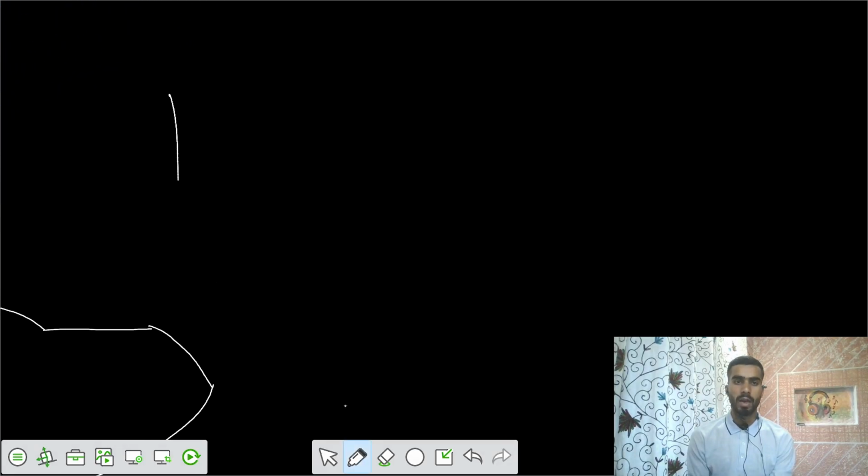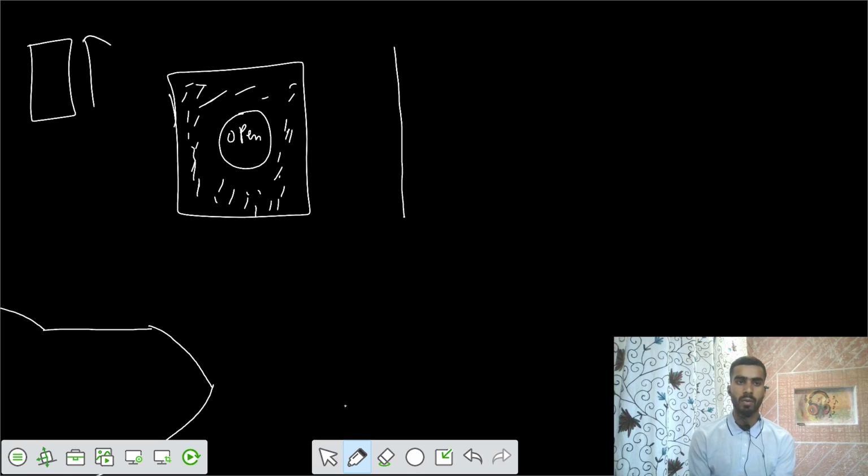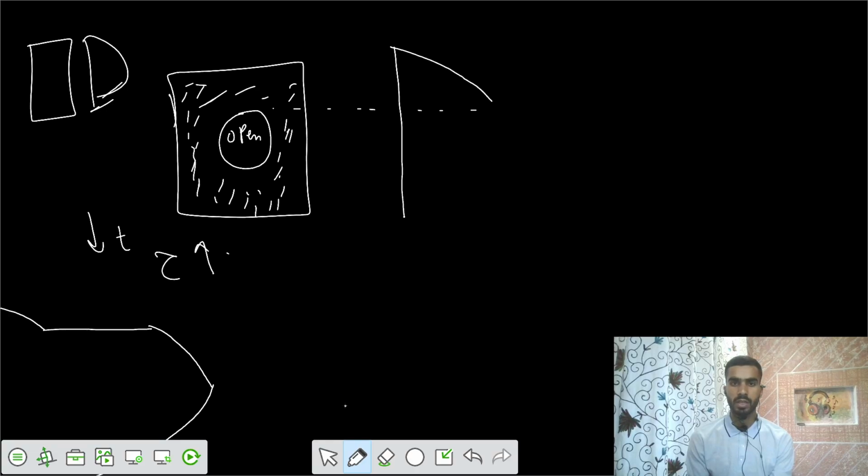Now if you have a rectangular section, but you have cut the mid part, so this is open, we have only this part now. Your solid part is only this one. Had it been a rectangular section, I would have drawn it in this fashion. So after this point we can have this variation. Then after that we have a decrease of thickness. Thickness decreases, that means shear stress would increase. Similarly from both sides the shear stress increases, then it can go to some value. So this is your variation.